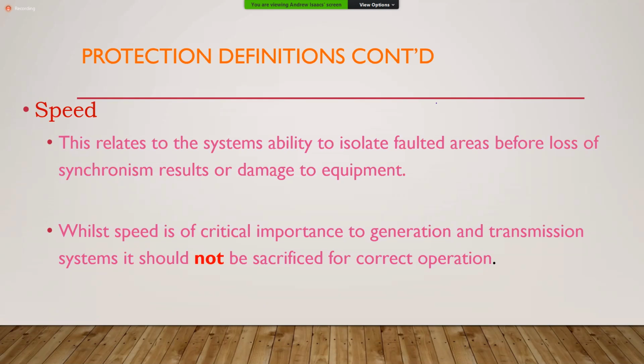Yes? So the point we're making here is that in designing your protection system, you must be cognizant of that, because the fault cannot remain on the system beyond the critical clearing time. That critical clearing time that you have calculated is what you would use to represent the maximum, or should I say, the limit in terms of operation of your protection system to clear whatever fault there is.